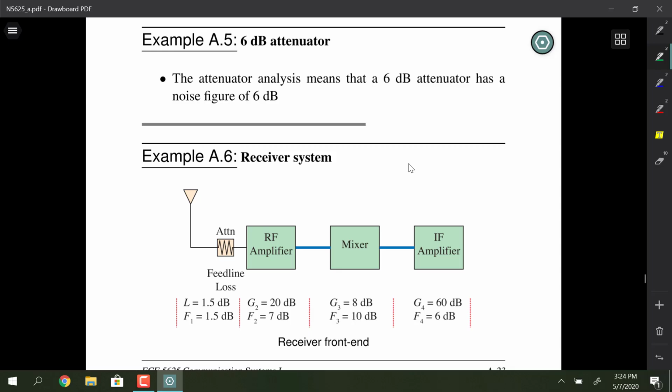And you might be curious as to how they power things. Well, they can send power over the RF cable itself. It's the same idea that audio recording studios use too. It's called phantom feed, where you actually send some power down the coax line, and that can drive the preamp.